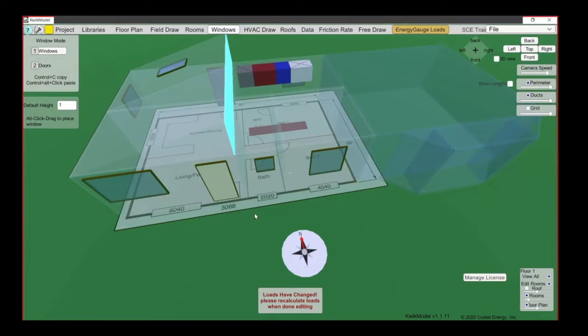So you need to size your air conditioners. That's the whole purpose of Manual J, or those 2 calculations: how fast, in BTUs per hour, is the heat coming into the house in the summertime, and how fast, in BTUs per hour, is the heat leaving the house in the wintertime. And you can do that on what we call a block load, which is the entire house all at once, and that will allow you to size your furnace and your air conditioner. But we need more information than that because we need to also size ductwork. And so instead of doing a block load for the entire house, we're going to do room by room loads. And instead of calculating that BTUs per hour for the entire house, it's going to separate it into rooms.